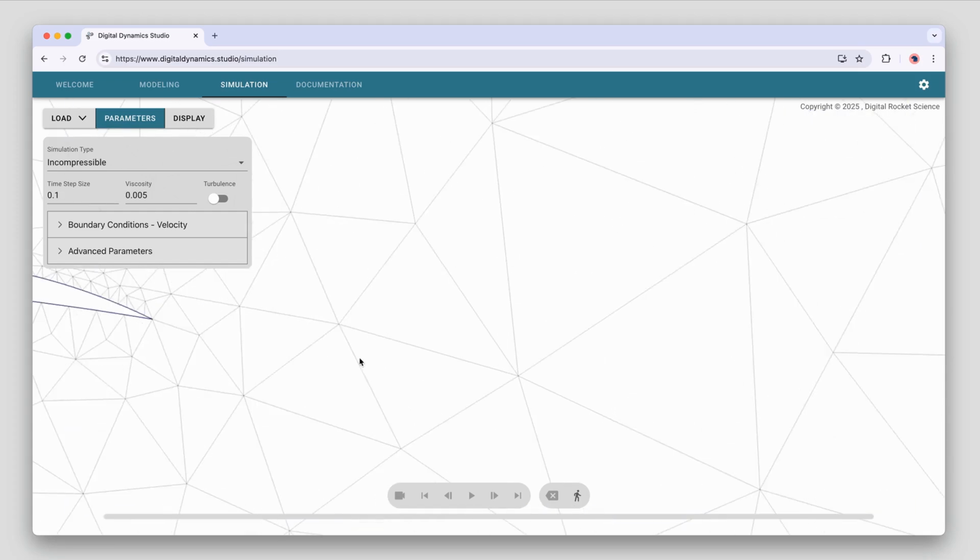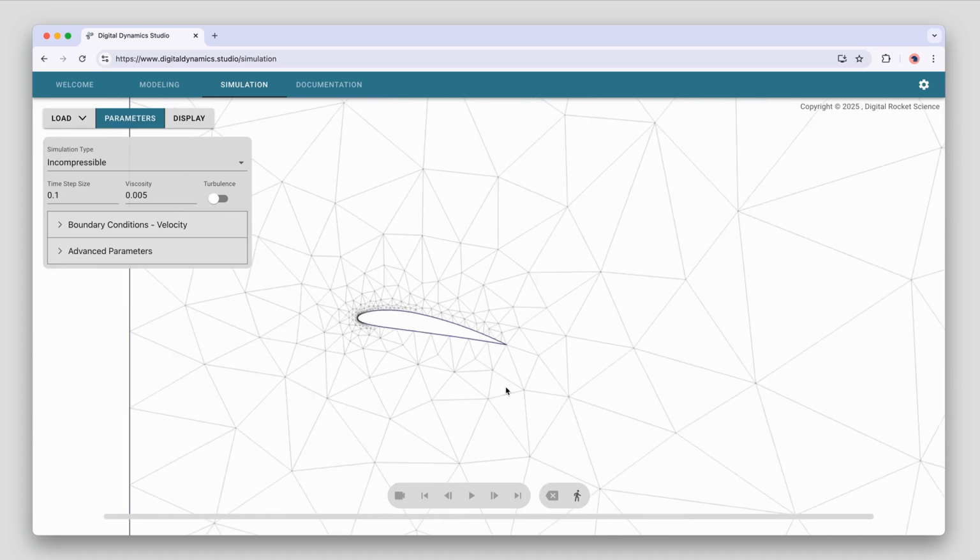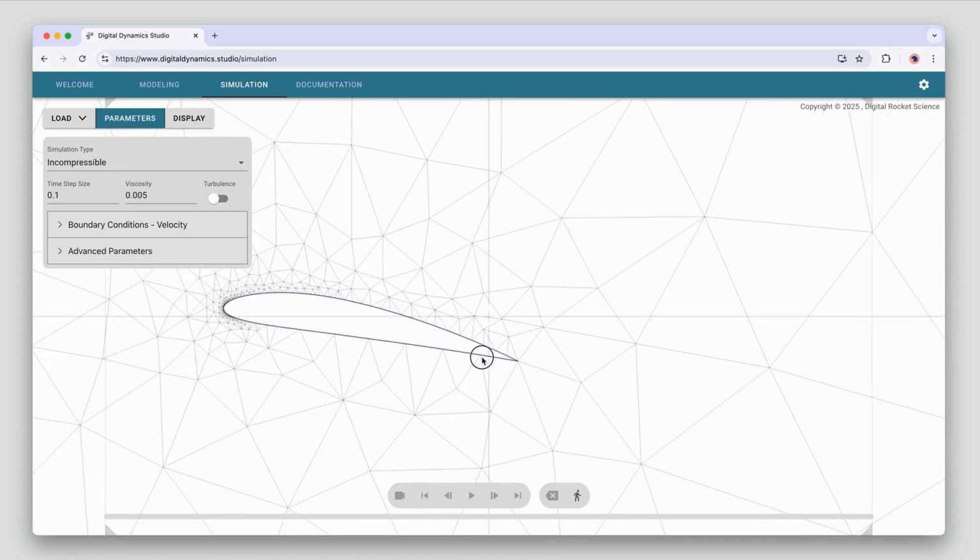And it's kind of like a movie, where a movie is constructed of a series of images that when played back together show what's happening in the movie. Pretty much the same thing happens here. We're going to compute the solution at a bunch of individual frames, and that can be played back to see how the fluid flow behaves. And the separation in time between each computational frame, each simulation frame, is the time step size.